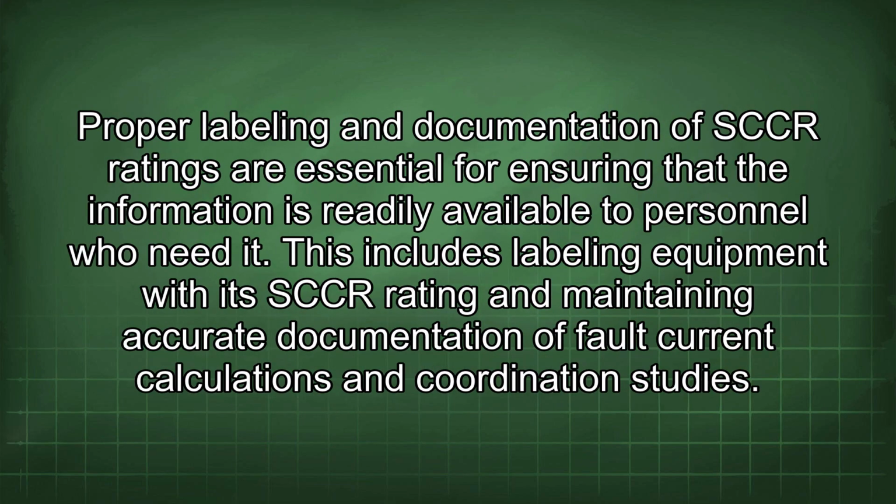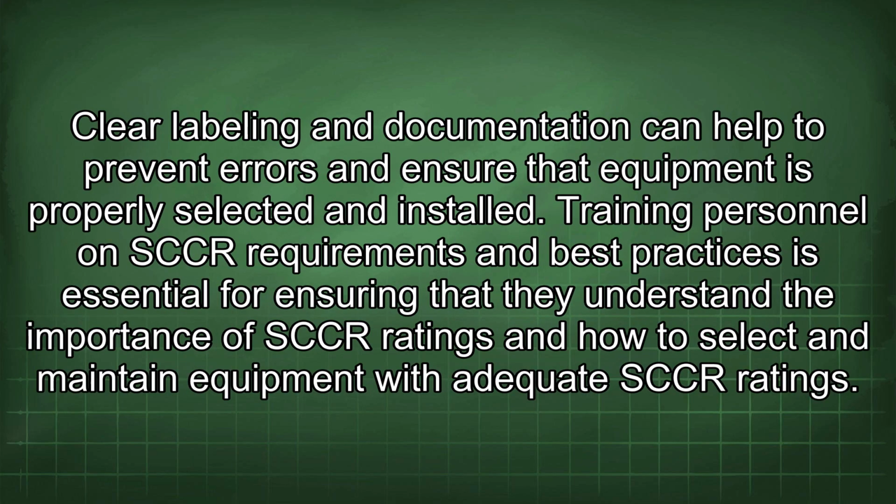Proper labeling and documentation of SCCR ratings are essential for ensuring that the information is readily available to personnel who need it. This includes labeling equipment with its SCCR rating and maintaining accurate documentation of fault current calculations and coordination studies. Clear labeling and documentation can help to prevent errors and ensure that equipment is properly selected and installed.